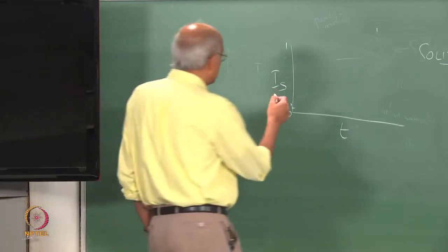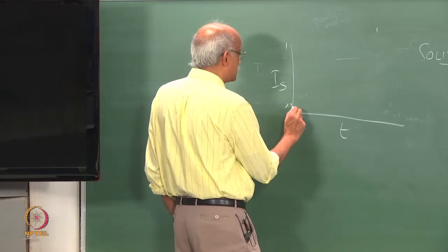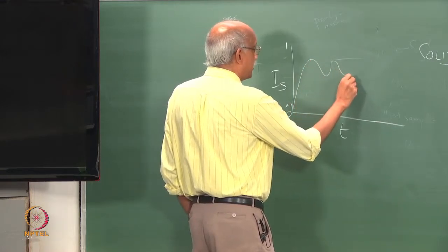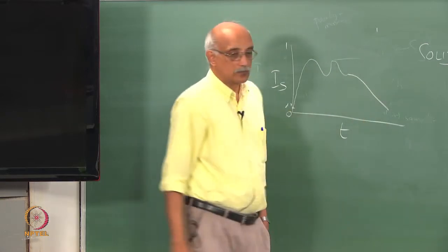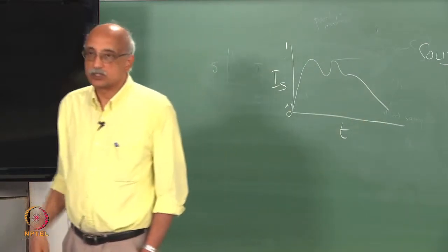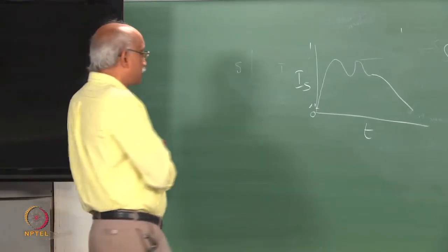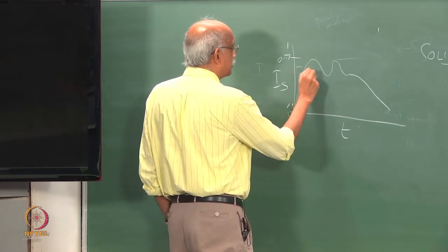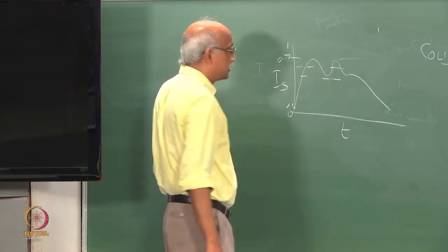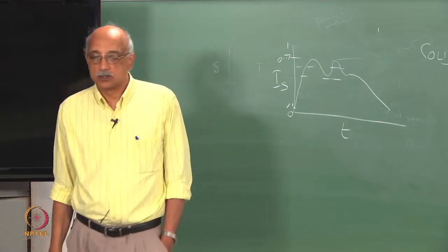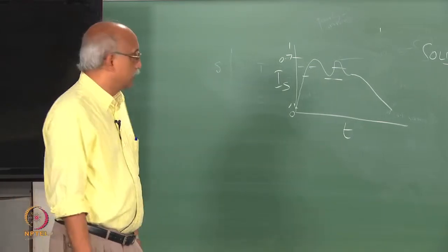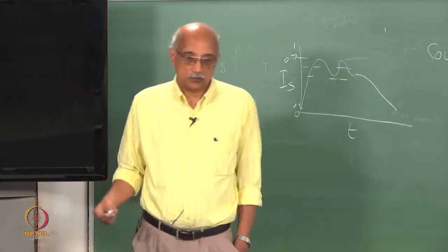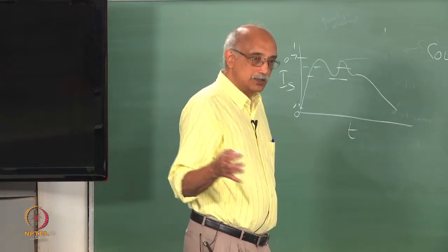So, if you look at how this behaves, the kind of behavior that you see is again initially there is a rapid rise, but then sort of a fluctuating behavior followed by a tendency for the mixing to get worse over time. So, in fact, the maximum you get to is about 0.7 or so, and then it starts fluctuating in this region between 0.4 to 0.5, and eventually it starts to take a dive. And again, the reason that this happens is for two reasons. One is just segregation and the other is agglomeration.